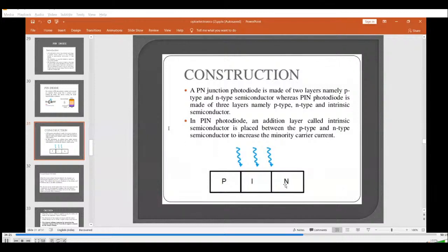So this forward current flows due to both electrons and holes. Therefore, in forward biased condition, the PIN diode acts like a current controlled variable resistance. Current controlled because resistivity is decreasing over here and conductivity is increased. That is why it acts like a current controlled variable resistance. So please remember such points from an objective point of view.